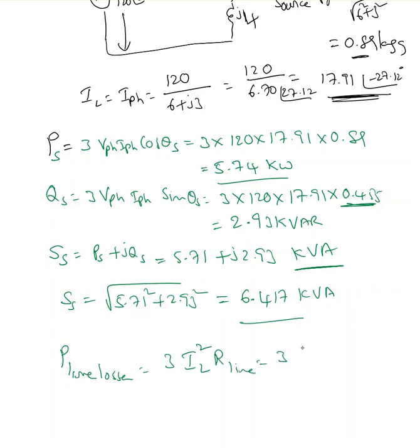Because it's star, the line current is the same as the phase current, 17.91. So this total power equals 968.76 watt. That's the power loss.